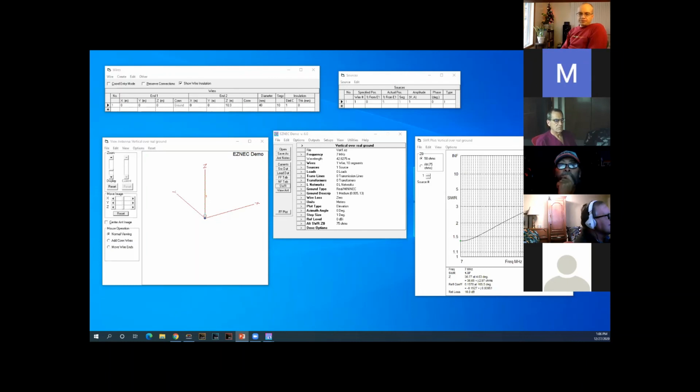And that's actually it. The whole purpose of this is just to show you what some of the buttons do. I think it's a great training tool for learning what's important with antennas and what isn't. Play with it, bend your antennas, take a look at it, raise the height, compare it to a vertical in the backyard. And when you really get good, you can do what Warren did. There are all kinds of pre-made antenna pattern files out there. You can get hex beams, 6-element Yagis, there are thousands of them that guys have put together. Go take a look at it, just play with it.